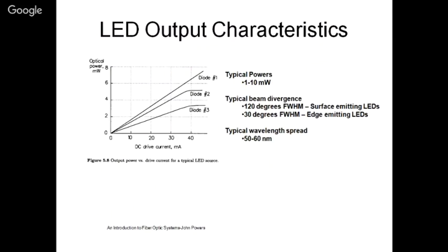So these are current control devices. The light depends upon the current flowing through the junction. So if we can change the current somehow with a signal, and launch this into optical fiber, we will be able to communicate. And the faster we can modulate, the faster will be the bit rate. So this was the basic foundation of thinking that optical fiber communication is going to be successful.